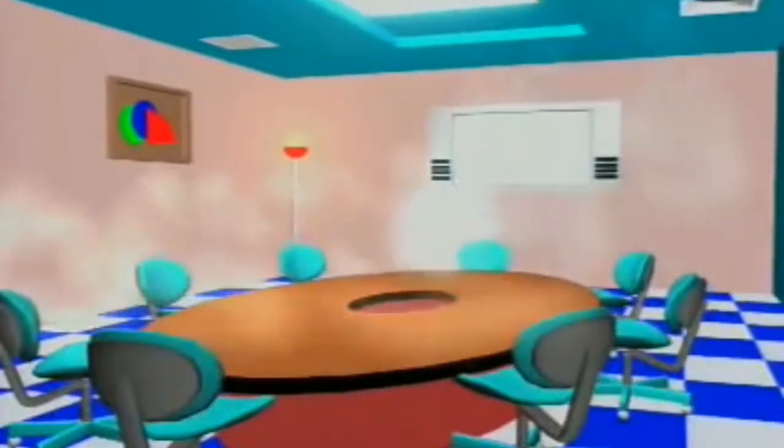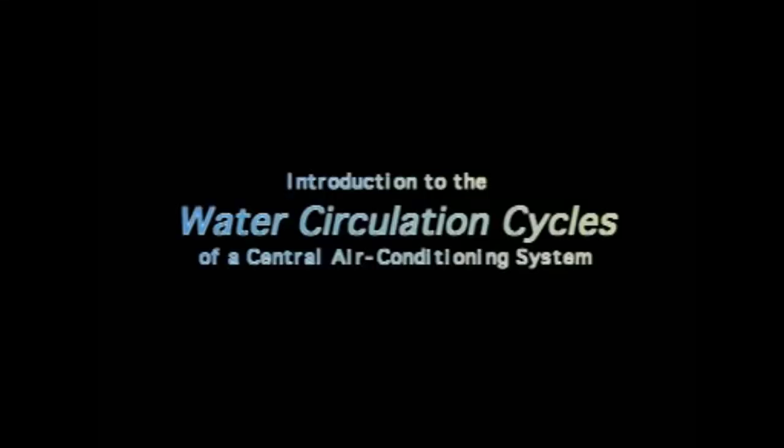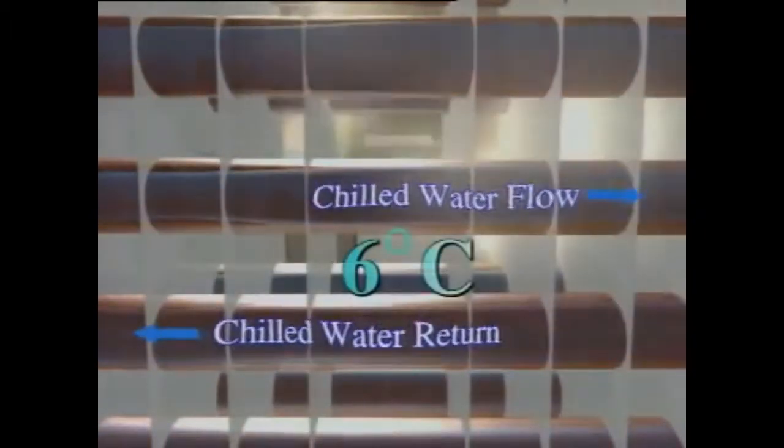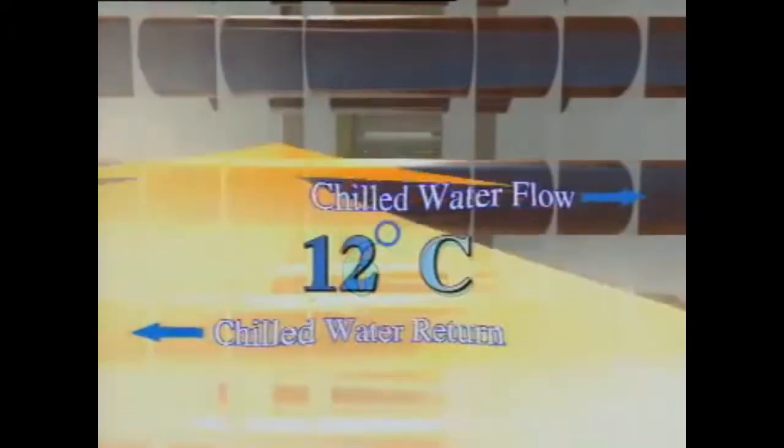After being cooled, the air is then delivered by the fan back to the room via the supply air duct. The cycle of air circulation repeats. The heat absorbed by the chilled water raises the temperature of the chilled water from 6 degrees Celsius to around 12 degrees Celsius.